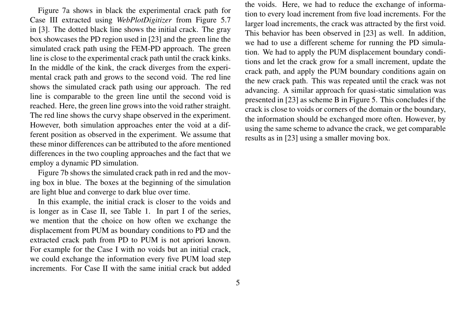The authors emphasize the importance of adaptively exchanging information between the PF and PD domains, depending on the crack's proximity to voids or domain boundaries. In case 3, with a longer initial crack closer to the voids, the authors had to reduce the exchange of information to every load increment, and employ a different scheme for running the PD simulation to achieve comparable results to the FEM-PD approach. This underscores the need to adapt the coupling scheme based on the specific problem configuration.